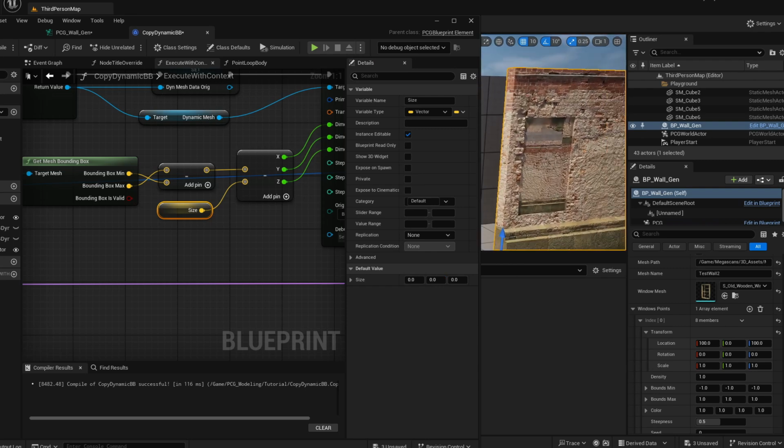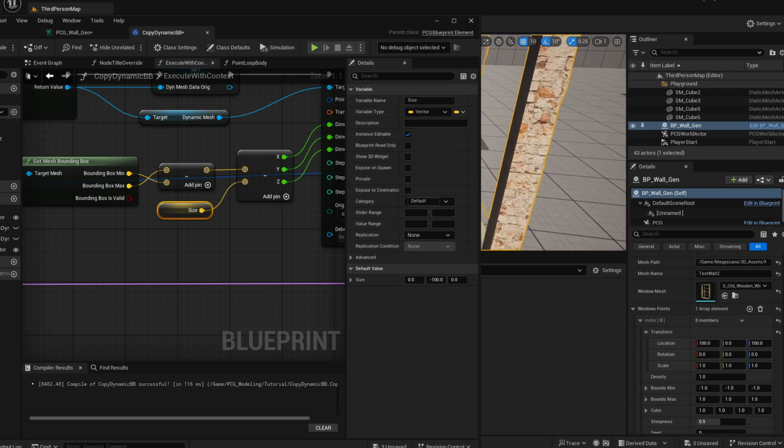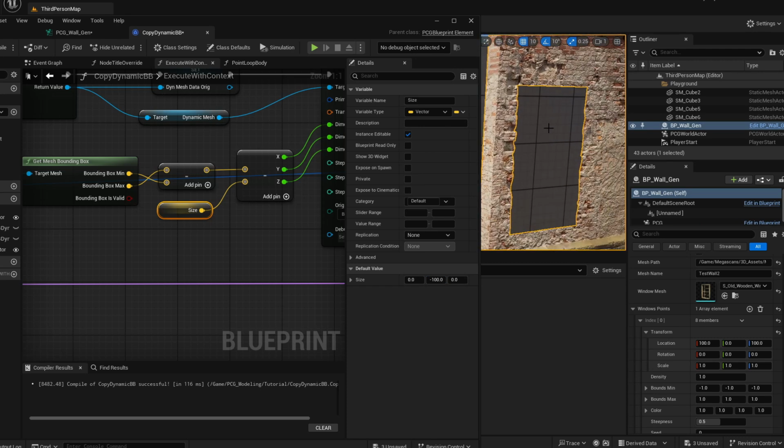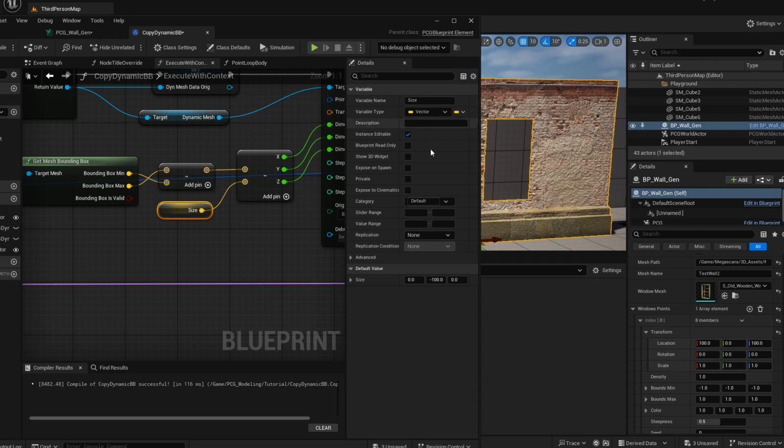And this is quite useful in this case because we want to make this box bigger and cut through the full wall. So this will accept negative values to make it bigger. So write minus 50, for example. Okay, minus 100 will do a full cutout in this wall for your window. And that's great. Let's test by